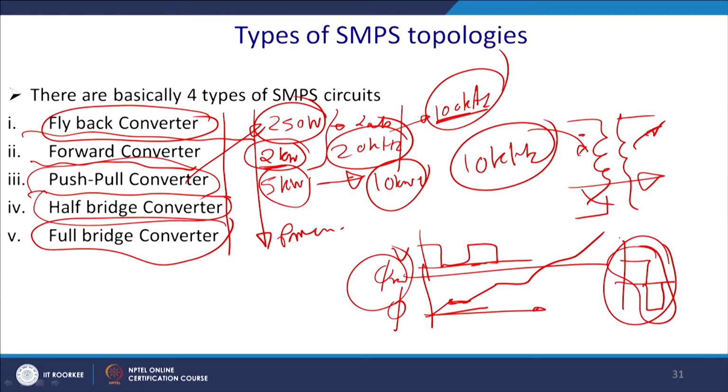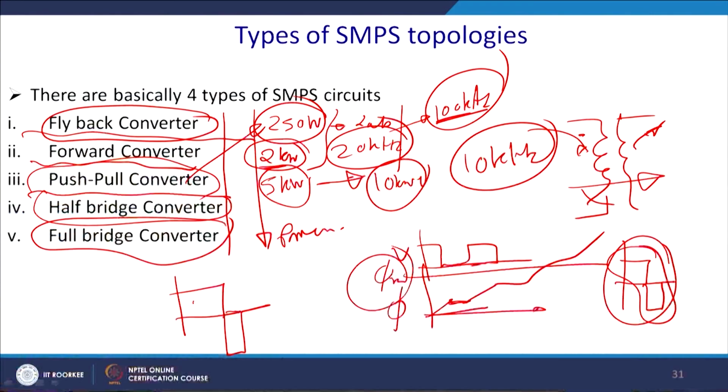This is the challenge of all these DC to DC converters. We will see that, and due to that the switch will have a high voltage stress. So, you want to have this kind of voltage applied, but you cannot continue to apply negative voltage for the same duration of time. What you essentially do is apply a higher voltage, and you try to reset this flux, this integration of the voltage time curve.